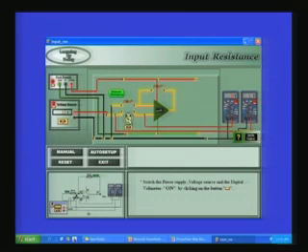Now what I do is I keep on increasing. The output voltage is 1 volt because both the resistors are 10k, 10k, equal. So that is why I am getting 1 volt. Now I will keep increasing the resistance till I get 0.5 volts across. Now it is 0.5 volts. So this multimeter measures the voltage at V3, this multimeter measures the voltage at the input, and therefore when it is 0.5 volts, then you know the value of the resistor that I have here in the variable resistor is the actual value of the internal resistance of the op amp.